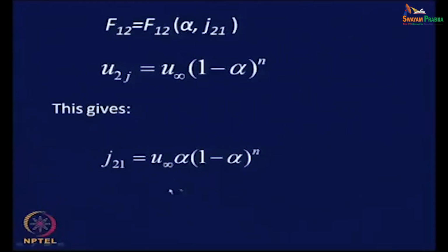So, this particular equation was obtained under the condition of steady state, inertia dominant, with absence of wall interaction effects and absence of particle-particle interaction. Now, when the particles come very close to one another, then particle-particle interaction becomes much more important. And when it becomes important, the basic assumption on the basis of which I had derived the equation for the curve itself fails.